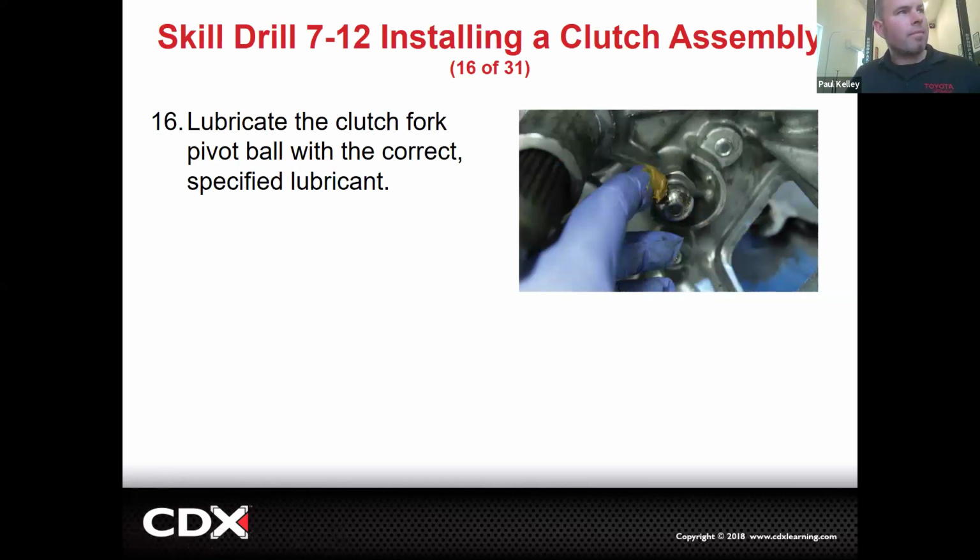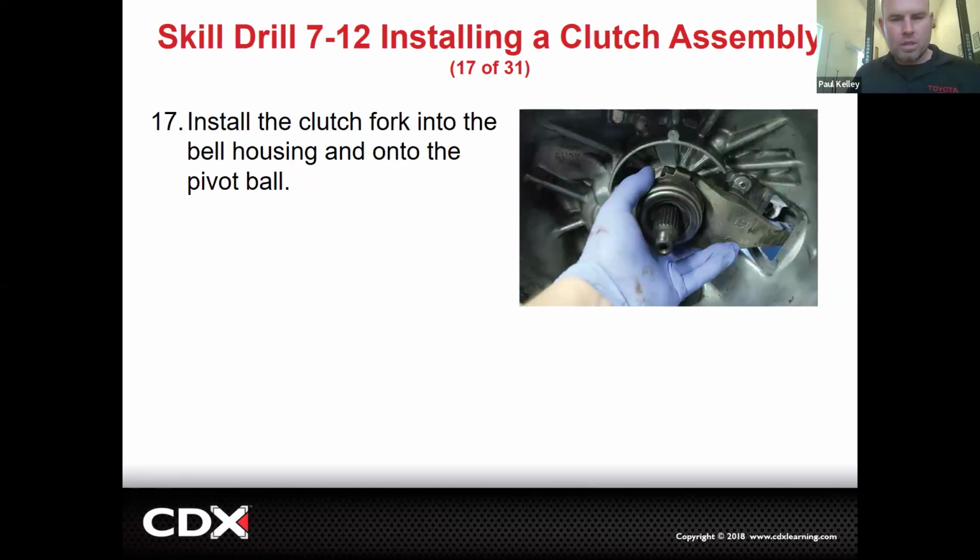Here's lubing that pivot. Again, with that nice high temperature grease right there. If you don't lube that pivot, that's the one that can go. And then you'd be like, oh, I need a new clutch, but you just did it 3 months ago. They'd be like, no, I did the new clutch. I just didn't lube the right part. So I look stupid. Kind of like lubing the guide pins and brakes, right?